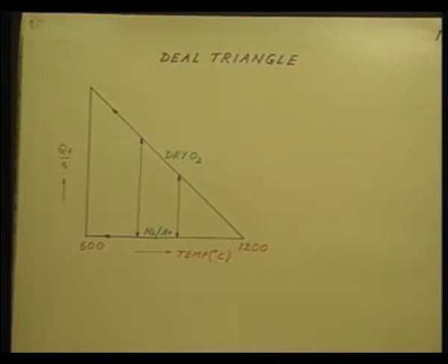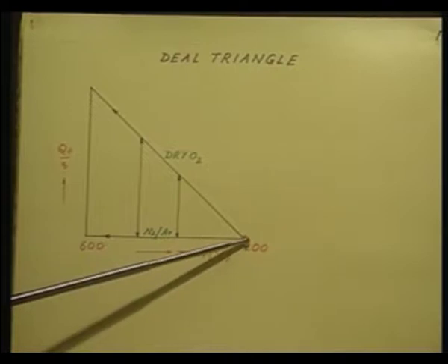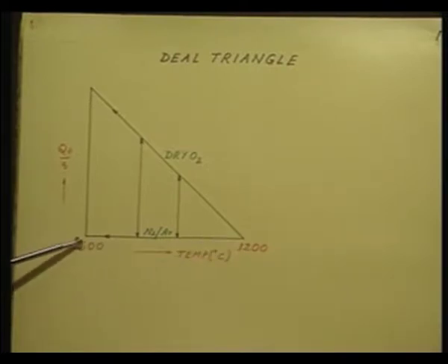inert ambient. So, in this inert ambient oxidation is entirely stopped, oxidation is not taking place, therefore, there is no question of incomplete oxidation. Whatever oxidation took place at very high temperature, and at that high temperature, since oxidation rates were much faster, there was much less chance of having incomplete oxidation. So, then one follows this baseline and you end up with a much lower fixed oxide charge. So, this is the standard practice today.